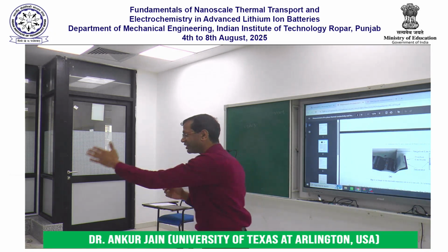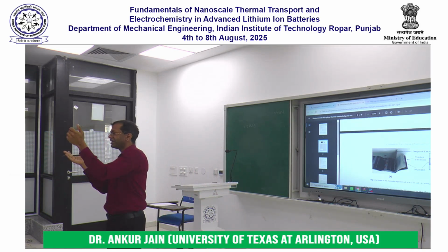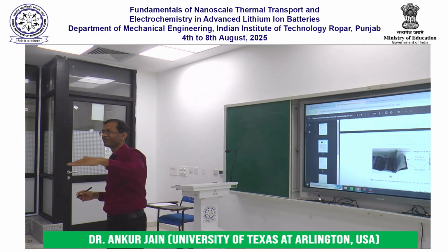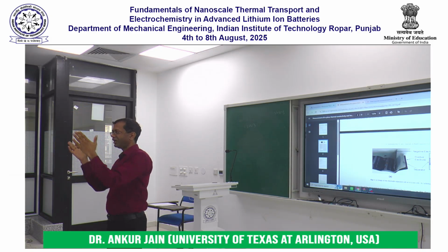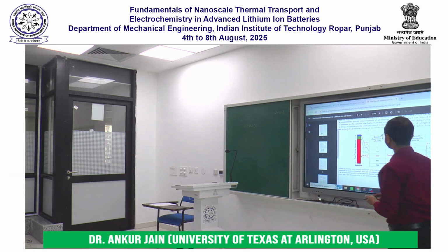If you have one material which is slightly positively charged, the other material which is slightly negatively charged, they will come together very nicely and they will adhere very well, and the heat will be able to transfer from one to the other very nicely. It all depends on the chemical composition of the interface, of the surface. If the two surfaces don't like each other, no matter how much you push them, they will never really intimately connect with each other. And we suspected that that is exactly what was going on here.